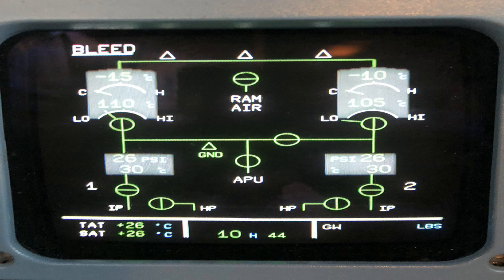Okay. So remember I mentioned the transducers. You do have 2 pressure transducers that are monitoring the air pressure available in the circuit. And the BMCs are monitoring the electrical signals from micro switches of the valves, also the temperature at the precooler outlet, and the transferred and the regulated pressures. All right, so that kind of gives you an idea.